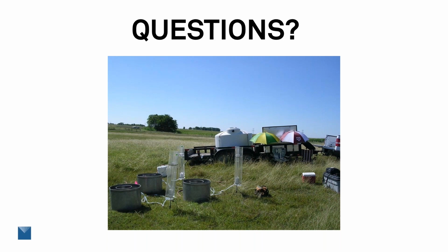So cracks can really impact your measurements, but they're really hard to measure because they can transmit so much water. My recommendation is to try and make your measurements when the soil isn't cracked. That way you have a better measurement of the intrinsic soil properties themselves. And if you know the soils are cracking, we can use modeling to estimate the amount of water that would flow through the crack depending on the size, because that's a relatively easy thing to estimate if we can estimate the crack sizes. But it's really hard to deal with expansive soils. Expansive soils make a lot of measurements tricky.